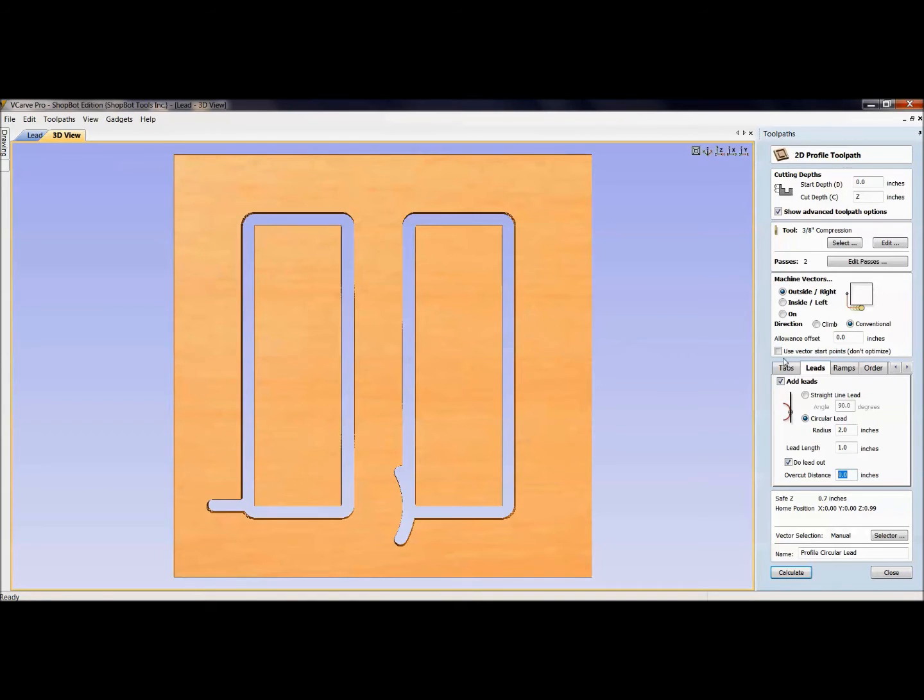But usually with your sharp bits, your machine dialed in, and a good ramp, which we'll show you in the video, you don't have to worry too much about this overcut. But what we're going to be showing in the video is we cannot use just a straight lead here into the material. My lead actually has to start either off the material, or I've had to make another toolpath ahead of time. So with that being said, let's step away from the software here for a second, and we'll look into a project which applies tabs, leads, ramps, and orders all into making it a more efficient cut.